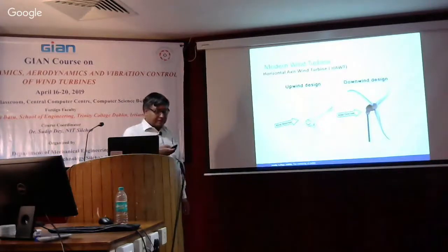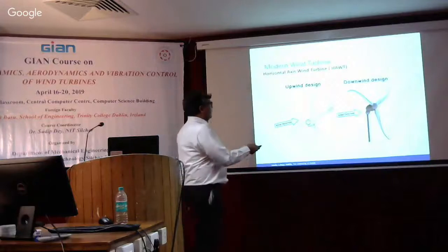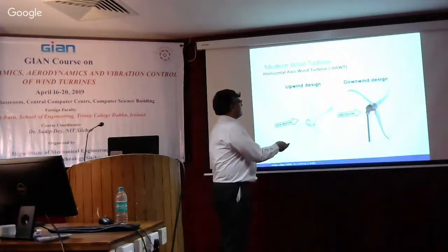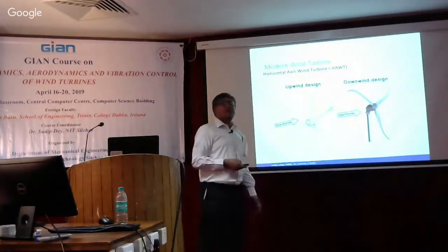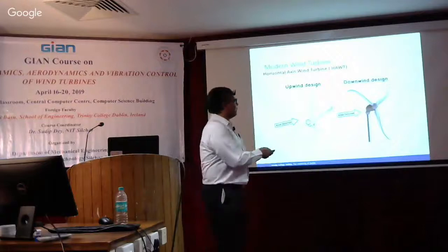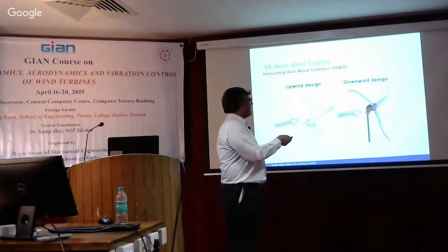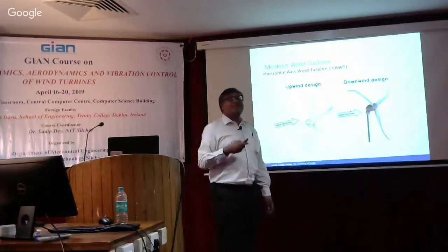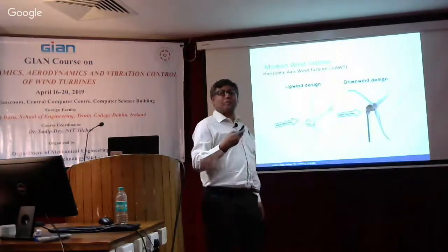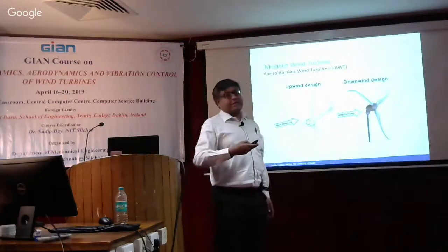So obviously all of the wind is not able to pass freely, and there is what is called a deficit of wind created following the obstruction by the tower. Every time a blade passes the tower, it feels that suddenly there is a drop in the air velocity.